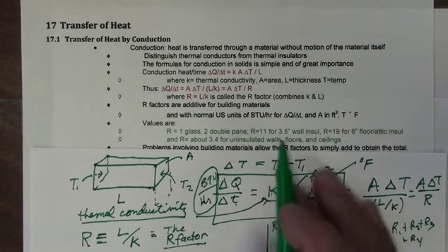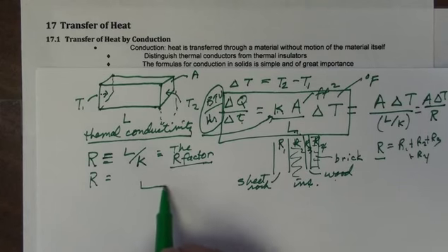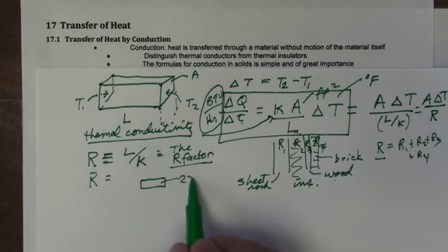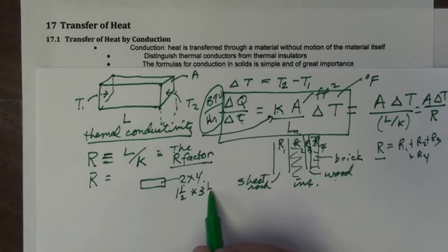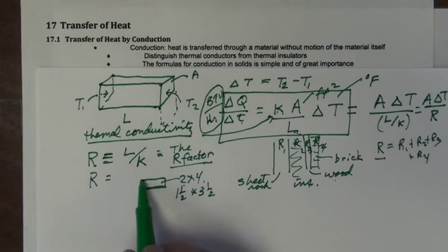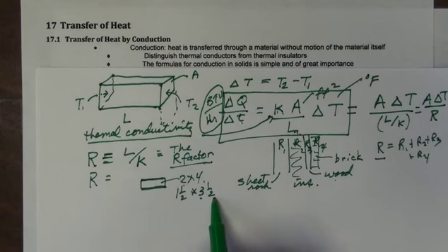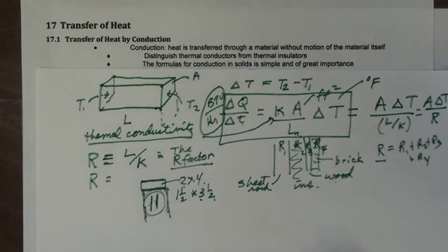Now you may say, well, what, 3.5 inches? It turns out that walls are made of 2x4s. But a 2x4 doesn't measure 2 inches by 4 inches. A 2x4 measures 1.5 by 3.5. The rest of that got taken away in the sawing process. So in fact, the walls in all ordinary houses are 3.5 inches thick. So they make the insulation 3.5 inches thick in what are called batts. They're like blankets of insulation that roll out and exactly fill that 3.5 inches. And they have an R factor of 11.